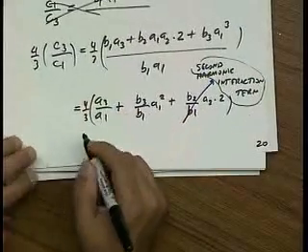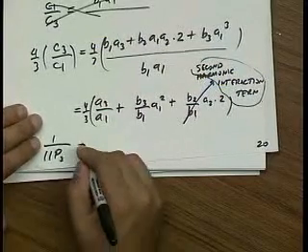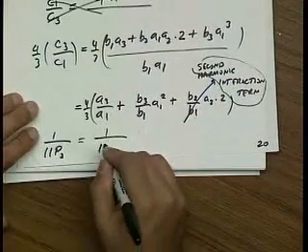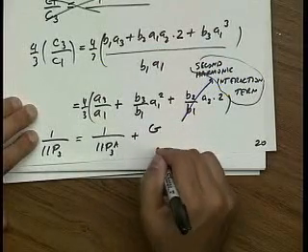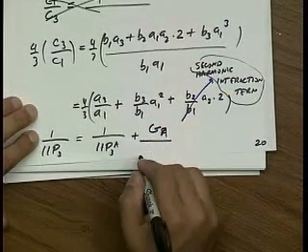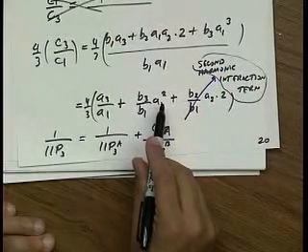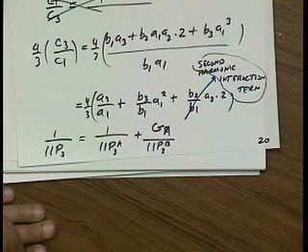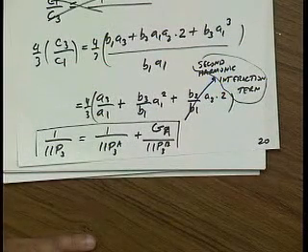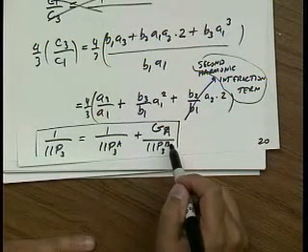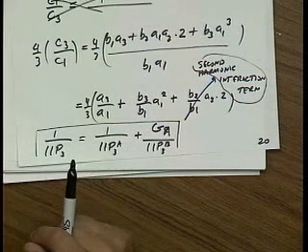here by 4/3, I can write this as 1 over the input IP3 of the overall amplifier, the cascade, is equal to 1 over the input IP3 of amplifier A, that's this term, plus power gain of amplifier A, over input IP3 of amplifier B. Okay? This is the power gain because it's the voltage gain squared. So now the formula for input IP3 looks nice and simple. It looks just like the case of the IP2 point. I input refer the IP3 of my second amplifier by the power gain, and then I take them in parallel. Okay? Now, you guys can hopefully see the error I made before.